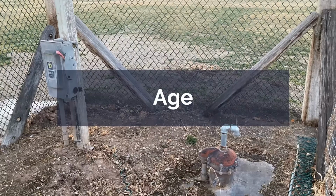Age is also important. Somebody mentioned that in the chat before. That's a really important thing, although it often isn't the best predictor of lifespan. It is really good to know when something was installed, so that when you're evaluating assets, you can extrapolate their condition from other similarly aged and placed assets. It's not the only factor, but it certainly is a factor. If well pumps in your system typically last 15 years, you're going to want to know when you're approaching that 15-year mark, so that you can think about replacing it, or at least make plans to reassess its condition more often and keep closer track of the deterioration.